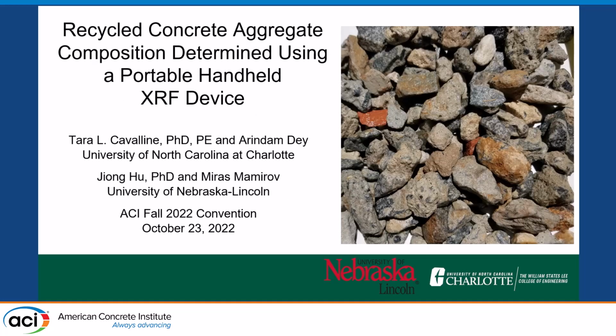Going back real quick, our work was essentially to try to give more rapid characterization to recycled concrete aggregates. One of our biggest challenges to folks actually using this is that they're nervous about it. They're not quite sure what it contains, how much mortar content is in it, what type of contamination might be in it. And in all actuality, this is just one piece of a series of tests that we developed, and we were targeting rapid, cheap, repeatable technologies